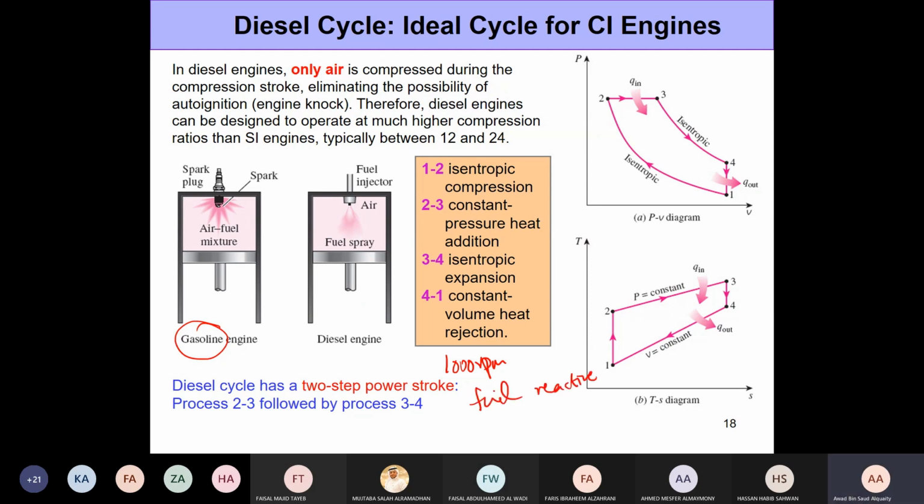Gasoline, or as you say, benzene here, is not very reactive. Diesel fuel is more reactive. So it is about selecting the correct chemical or the correct fuel. You want the ignition to happen immediately when you inject the fuel. That's the reason why we make use of diesel. Gasoline will not do the same job.